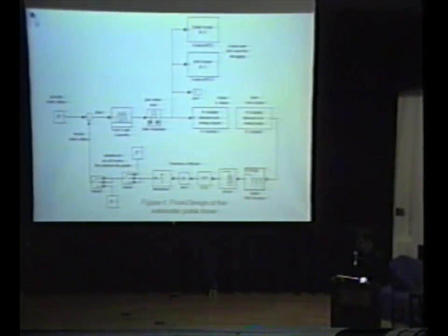This is the final design of the controller. Over here is the input from the guitar into the capture card for the computer. It then goes down to a filter. This is a low-pass filter which allows just the fundamental frequency of the note to pass through and filters out all the harmonics of the note. It then goes into a buffer. The buffer is needed to find the maximum value later on. So it puts this data into a buffer and sends the array to the FFT.